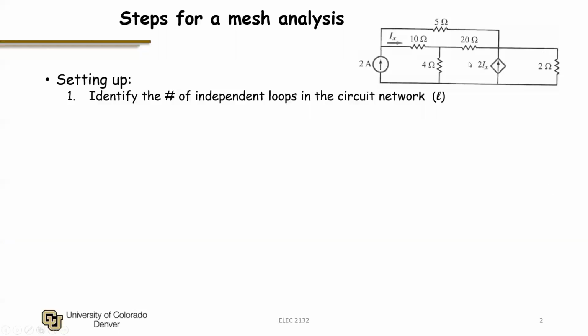So I have a circuit up here on the upper right. It's a two-dimensional circuit, so it's composed of a simple graph. And the number of loops in this network is simply the number of holes in the network, which we see is going to be 4. So we have first identified that the number of independent loops for that particular network would be 4.